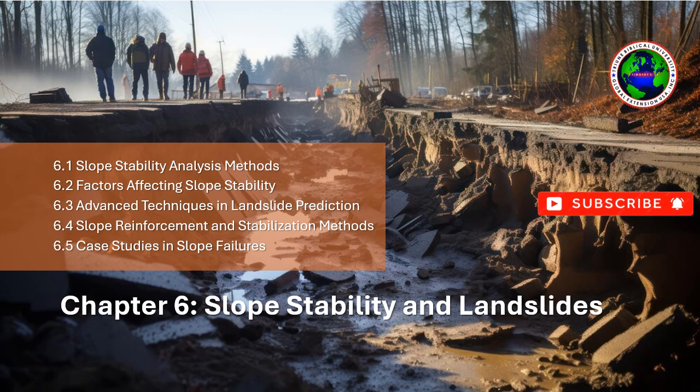6.2.4 Geological and structural factors. The underlying geological structure and the presence of various features within the slope influence its stability. Faults, fractures, bedding planes, and soil layering can either enhance or undermine slope integrity.